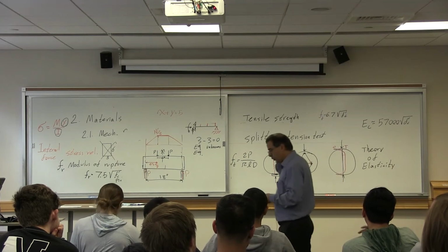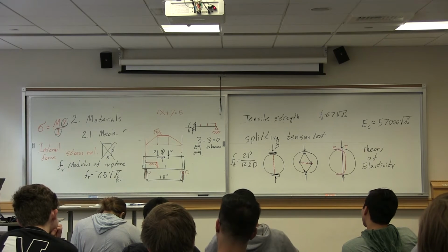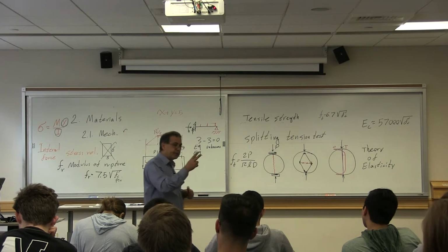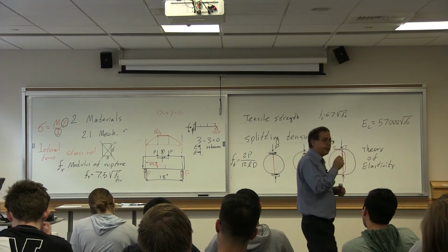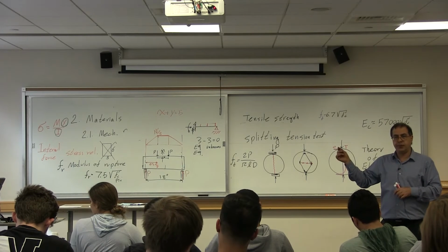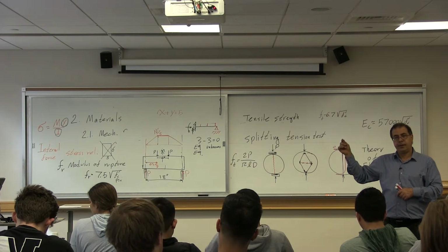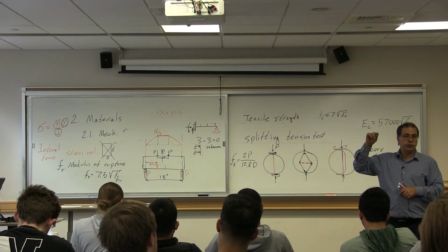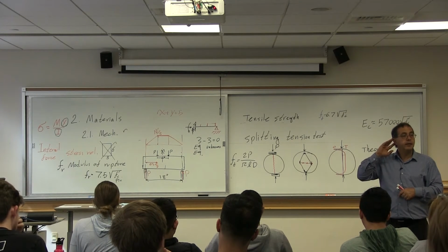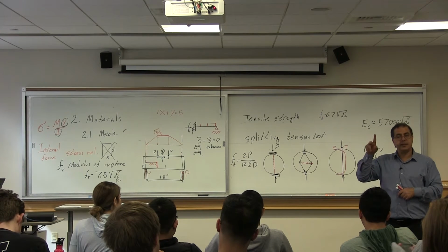So just going through the process one more time. If the number of equations is less than the number of unknowns in a structure, you would know that exactly the difference of those two is the number of compatibility equations you have. There is no way to have one more. If you had one more, what would happen? If you had two equations, one unknown, what would happen? Wouldn't it be unique? Not unique, not infinite, something else.